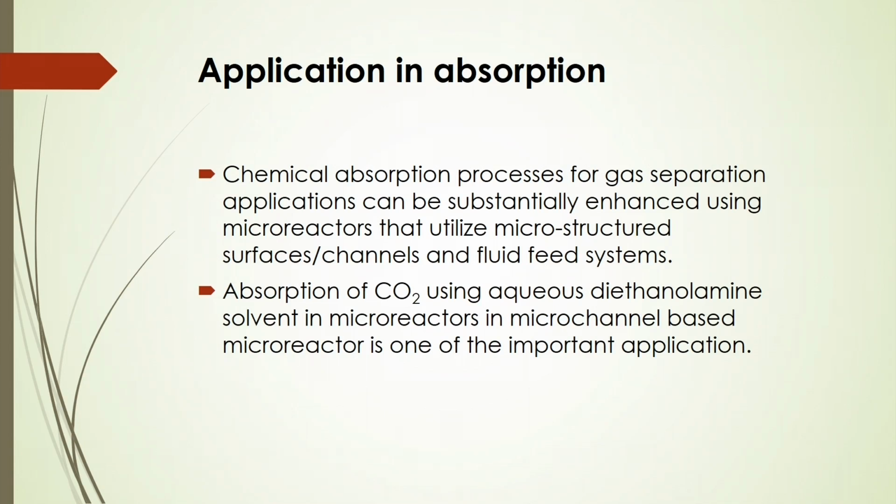Let us see other applications of the microreactors, like absorption reactions, chemical absorption processes for gas separation applications, that can be substantially enhanced using microreactors that utilize microstructured surfaces, channels, and fluid feed systems. If we consider the absorption of carbon dioxide using aqueous dimethylamine, or other amine solvents, you can use them in a microchannel based microreactor, and that is also an important aspect of process intensification for the separation of gases.